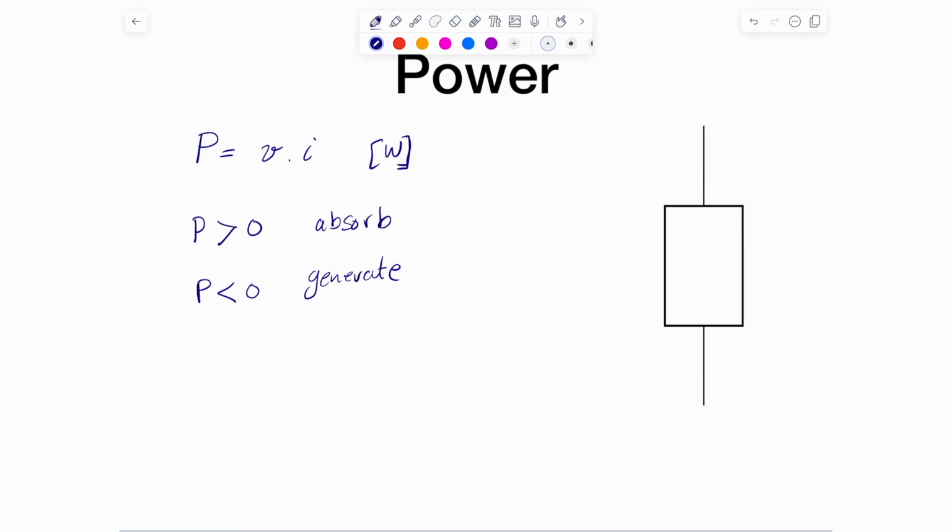Okay, all right, so let's take a look at a simple example to see how we can compute power. We have some sort of basic ideal circuit element, and I'm going to specify a voltage. When we specify a voltage, we have to specify a negative and a positive terminal, and the voltage value happens to be 2 volts in this case. I'll also say I have a current, leaving that positive terminal, going from the bottom all the way to the top. This current is 5 amps.